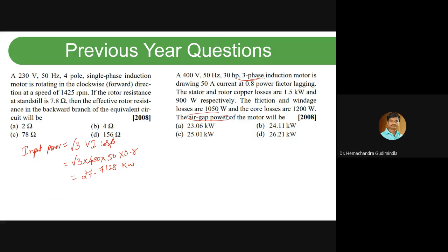Now, air gap power. What is the air gap power? Air gap power is the power between the stator and the rotor, right? So between the stator and rotor, what losses will exist?